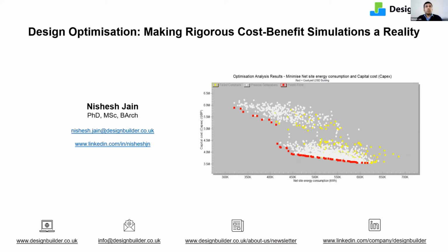Right now in DesignBuilder we use NSGA2 as the optimization engine, the algorithm which runs. These are efficient ones, and if for some number of generations you don't see any new Pareto optimal results, then there are chances that most of them are found.